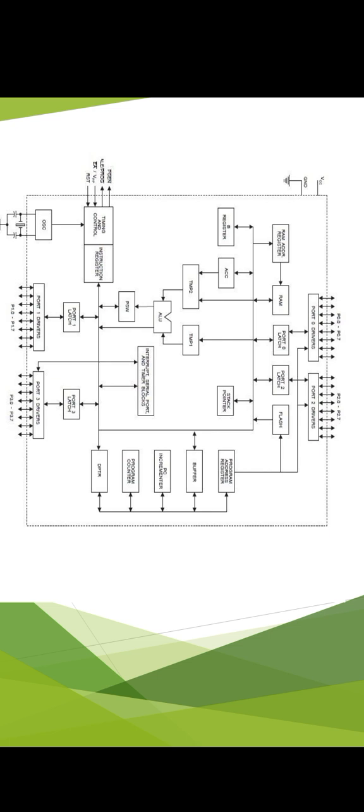The B register is an 8-bit register for storing a second operand for the ALU, as well as accumulating the result of an ALU operation for multiplication or division. PSW is the processor status word, a register to save the bits of different flags.